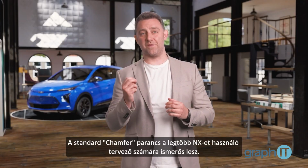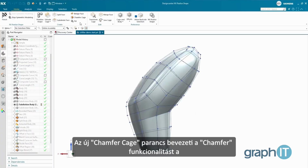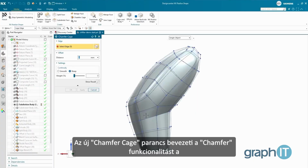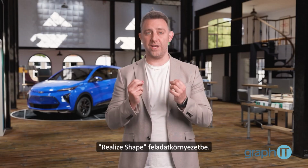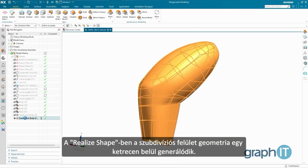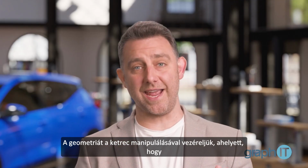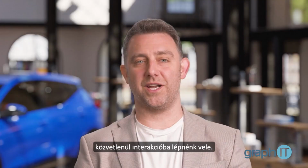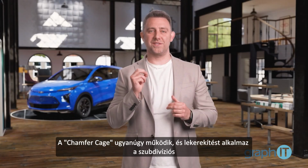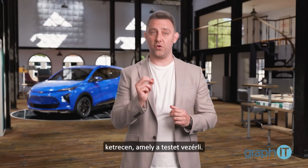The standard chamfer command will be familiar to most designers using NX. The new chamfer cage command brings chamfer functionality into the Realize Shape task environment. In Realize Shape, the subdivision surface geometry is generated within a cage. You control the geometry by manipulating the cage rather than interacting with it directly. Chamfer cage works the same way and applies a chamfer to the subdivision cage that controls the body.